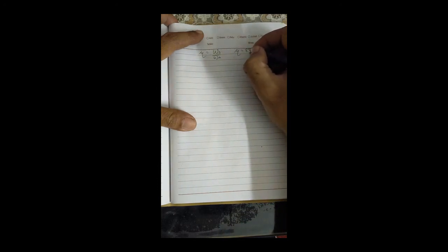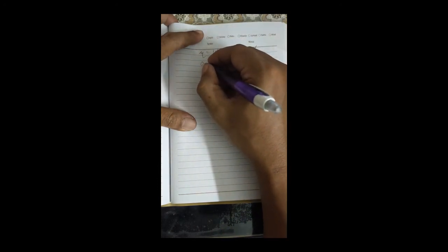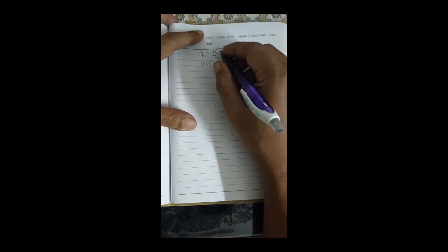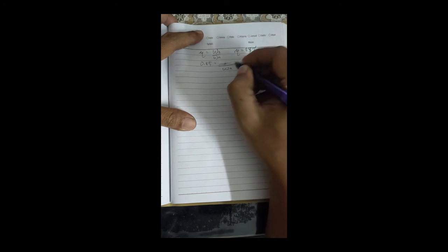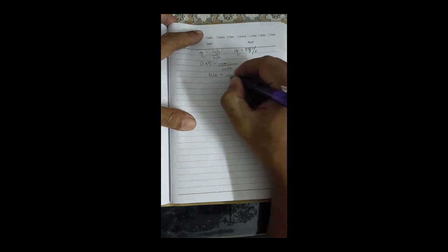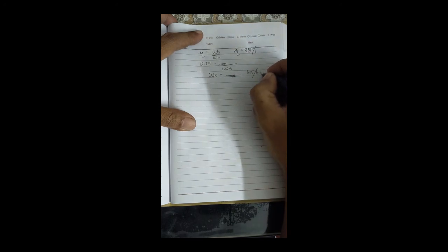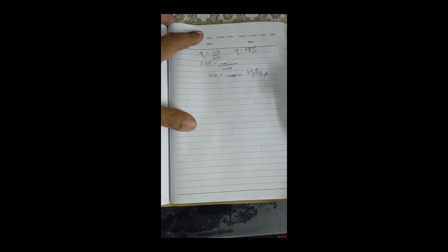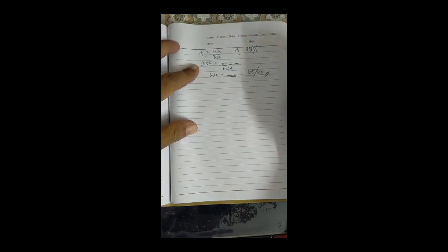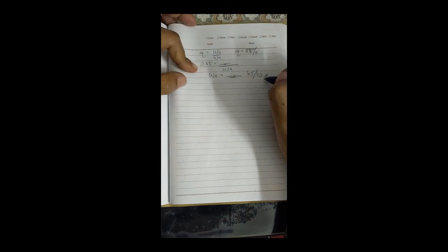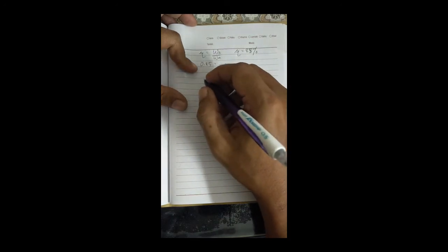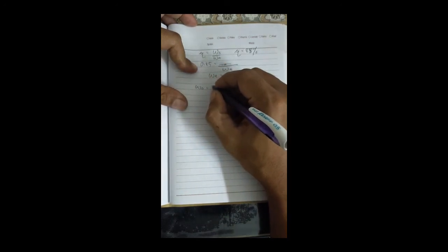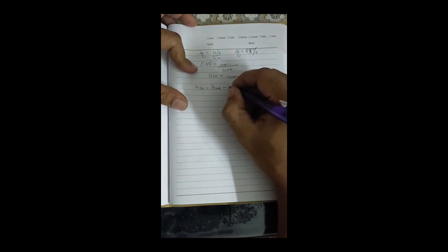85%, sorry, 85%. So 0.85, what is your just now divided by work actual. So work actual, kilojoule per kg. Okay, so that is the actual work. So just now you have calculated the isentropic work. Alright, so work actual is also H2 actual minus H1.